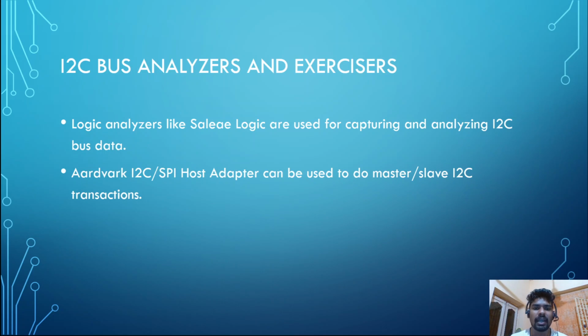Logic analyzers like Saleae Logic are used for capturing and analyzing the I2C bus data. There are I2C analyzers available with Saleae Logic that can be used for analyzing the data that was sent. We can also write our own proprietary protocol decoders on top of the I2C analyzer in Saleae Logic to decode proprietary protocols. And a hardware I2C spy host adapter can be used to exercise master or slave or both I2C communications.